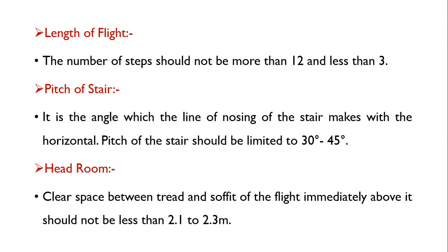So minimum 3 steps should be provided and maximum 12 steps can be provided in a single flight of stair. So the length of the flight, that is the number of steps, should not be more than 12 and should not be less than 3. If it is less than 3, then it won't come under the stair. If it is more than 12, in that case it will cause discomfort for users.